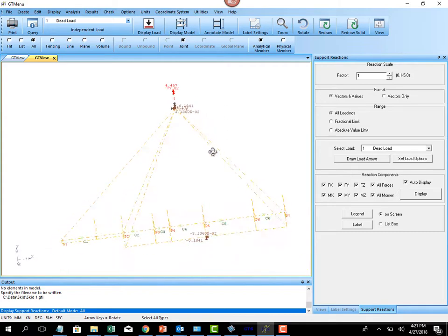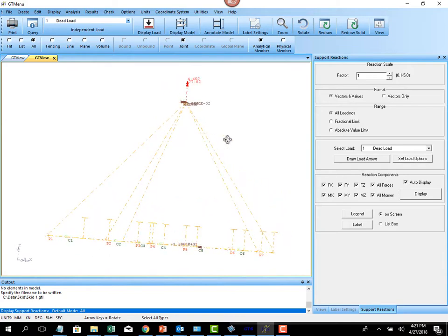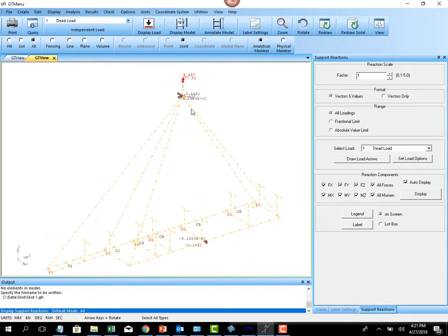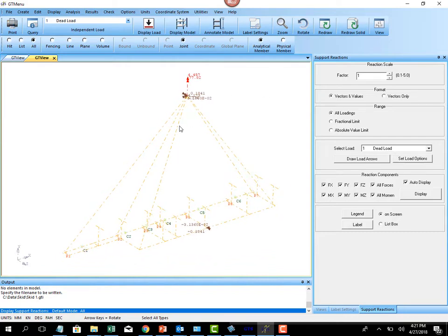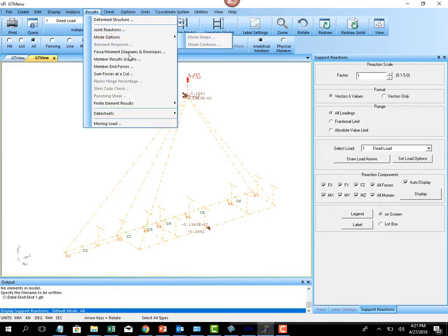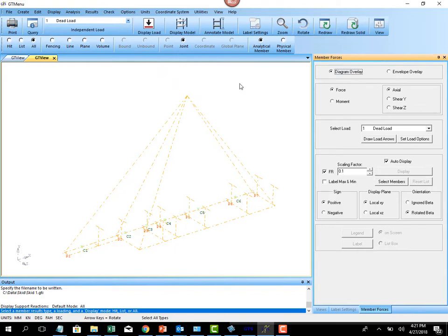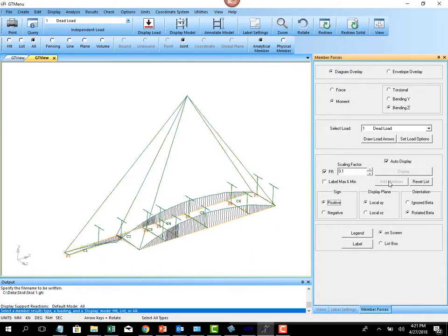Okay, first of all, you need to know if that crane can lift all this load. So this is the load that you can supply them with your factor of safety assigned to it. Then you might want to see results like the force and moment distribution. So let's say we want to see the moment diagram just to make sense out of how the skid is going to have this moment because of self weight. Here is the bending moment diagram for the skid beams, okay?